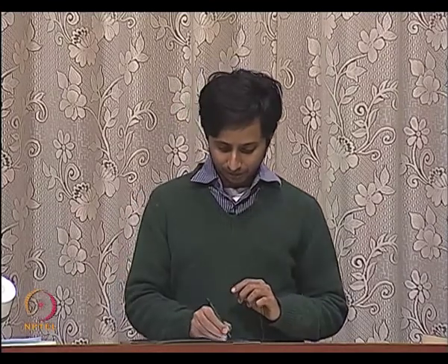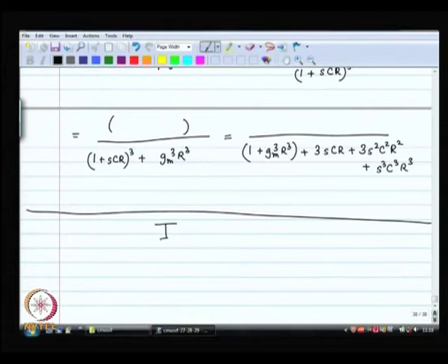Now, why I did this was to hint at the fact that suppose there is equilibrium, suppose you have designed your inverter very carefully, you have chosen the widths and lengths of the PMOS and NMOS devices very carefully, such that if VDD by 2 is the input, then VDD by 2 is the output precisely.